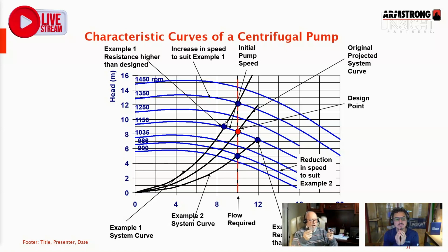At every point that a pipeline got to a piece of ductwork, there were 90s at every piece of ductwork. The mechanical contractor let the sheet metal contractor do the coordination drawings, and the sheet metal contractor went, well, the piping can't run through the ductwork, so I'll just put 90s to go down, over, and back up around every piece of ductwork. That added a whole bunch of uncalculated and unplanned for head loss in the system. Rather than change the elevation of the pipe or the duct so they didn't run into each other, the sheet metal contractor just thought, okay, I'll just add 90s. Talk about thoroughly destroying a job.